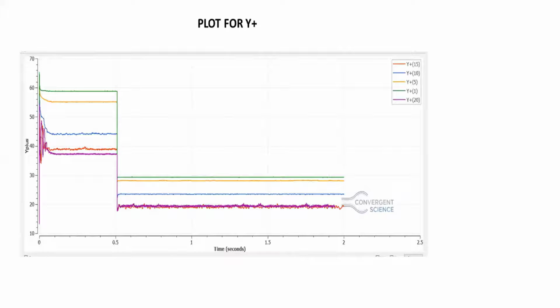We'll not talk much about Y plus, but yes, in the course, you will get to learn a lot about Y plus, and in fact, you are going to implement it. You are going to use Y plus calculator and everything to basically see, for these input conditions, what should be my Y plus, and depending upon that you will be doing the reverse calculation to see you are not overshooting on cell count.